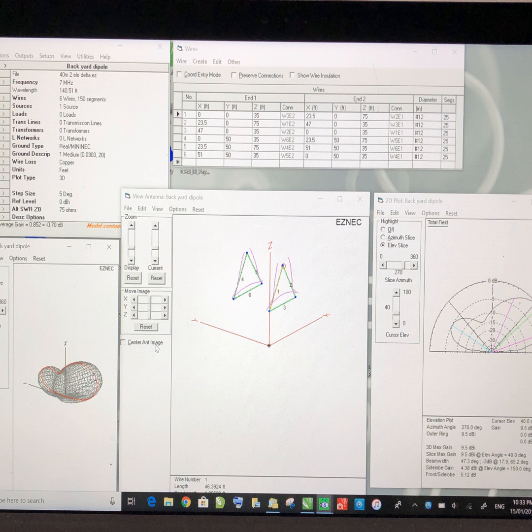Also, it does help if you're placing antennas close together. I have 2 towers here around about 15 meters apart, and if I build something on one tower and I've got an antenna on the other tower, inevitably there's some sort of interaction, particularly if the antennas happen to be pointing towards one another on various occasions. So you can plot this as well.